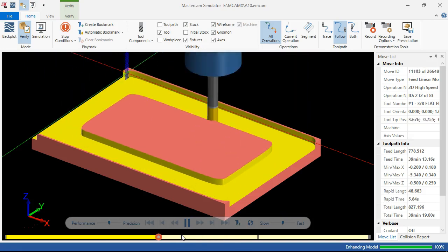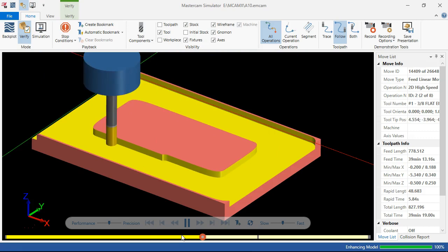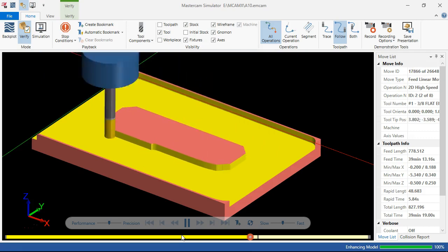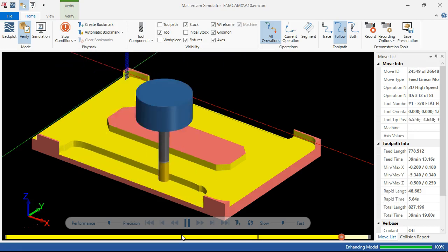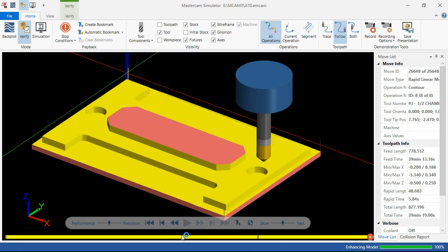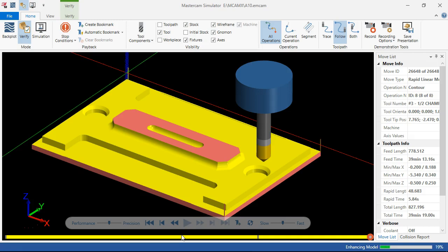So a nice thing about that dynamic mill is it is leaving the tool engaged. Those minor movements, it's generating a lot more code, but tool load is going to be much more consistent. All right.